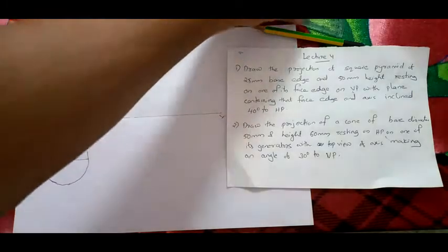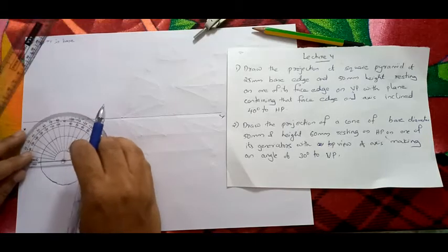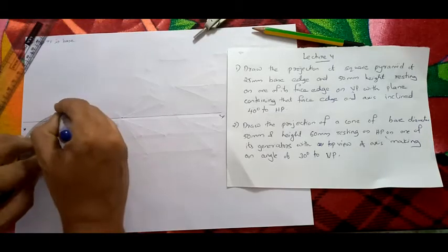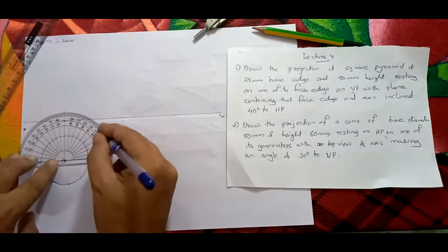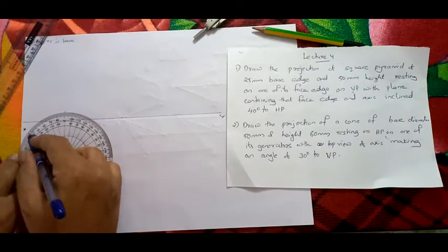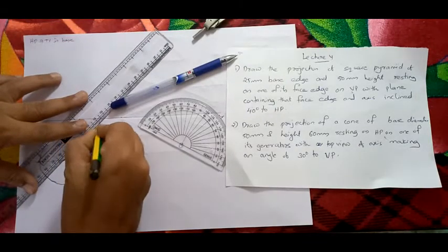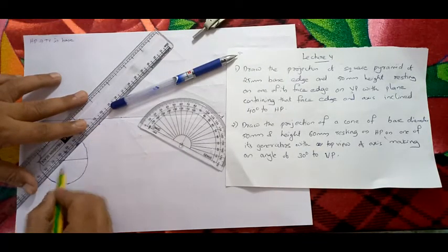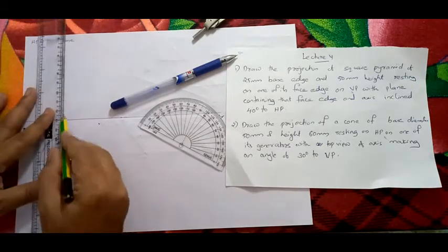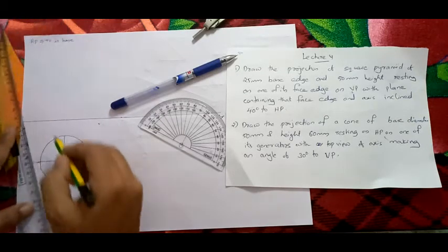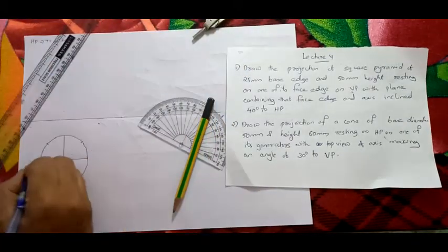How to divide it into 8 equal parts? Using this. See, now next, so taking it into 90. So we will take 90 degree, 45, 45, 90, 45. So we have taken 45 degree, 90 degree and 45 here, 135 degree. So next what we are going to do is, we will not be drawing lines here. Instead, see, I will place the scale here and mark the points here. Similarly, I will be drawing the perpendicular line here. Next, this 45 degree. Mark the points. So we have obtained points here.